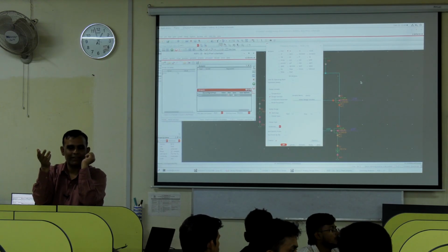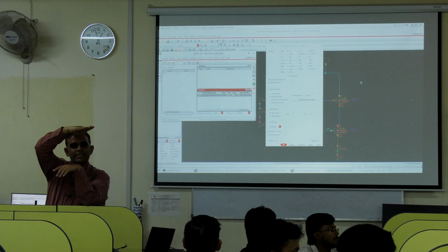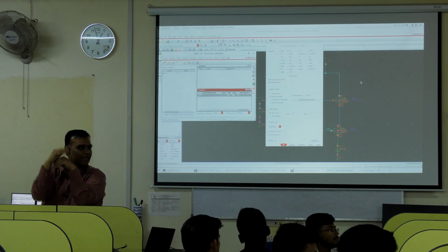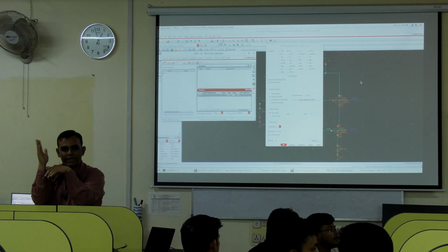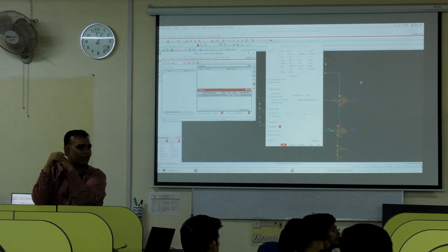Okay. So now here's a task for those who have already got it. Ignore the leakage current line. Just look at the line in between. Look at your output line, and if I have to model it as y is equal to m log x plus c, what is the value of m and c from your waveform? How will you go about finding it?